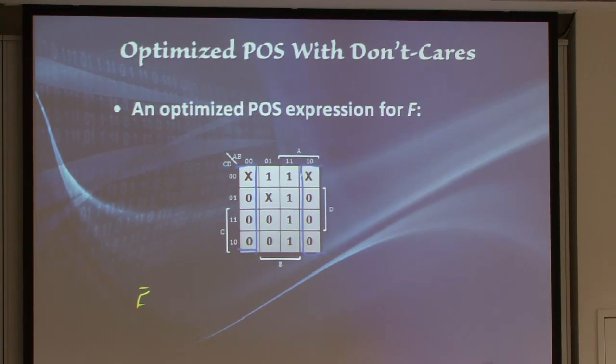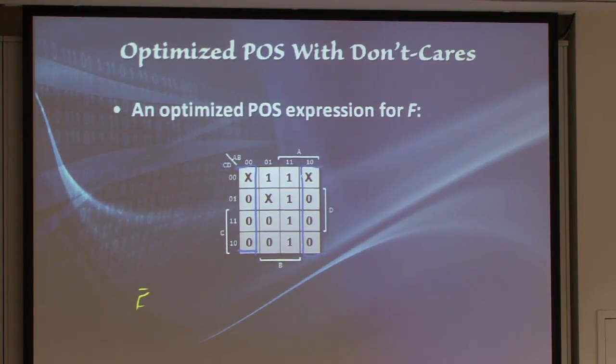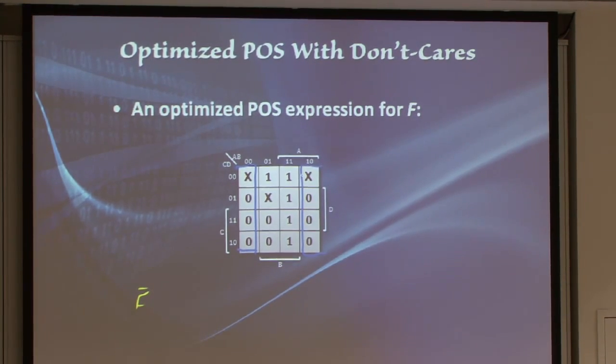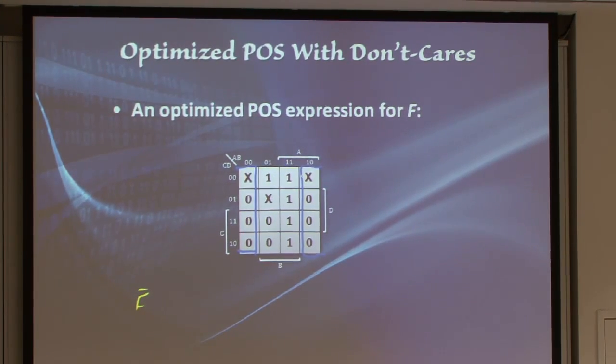Again, once I include them in our group, those don't cares will be pushed to 0. So when I implement the circuit and I put these combinations, the output from the circuit will be 0. There's no such thing as a don't care output for real. From a circuit, you either have a 0 output or a 1 output, which is a white lie because I will show you other outputs it could be, possibly on Friday, I think. Yep. As far as you're concerned, it can either be a 0 or 1.